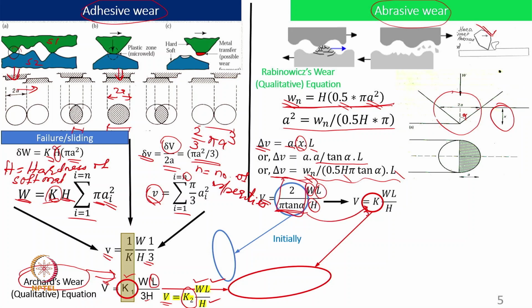However, this constant will vary depending on the condition of operation, but more or less this relation and the previous relation are the same. There is a wear volume, there is a normal load, there is a sliding distance, there is a hardness, and there is a multiplication constant also. So this is what has been given. Now this is what we have already shown about the top curve. When we give this kind of model, that model is going to represent only the b to c portion.